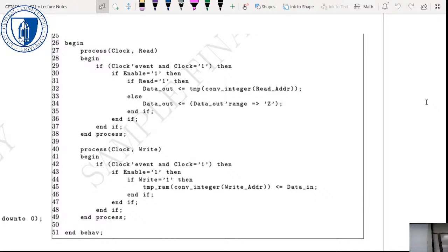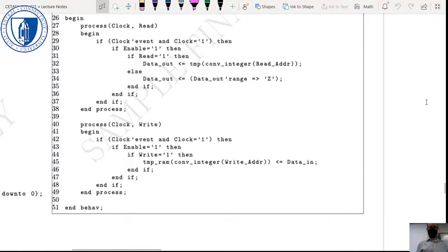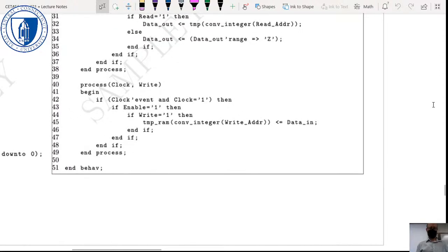I said earlier that everything in VHDL is in parallel, but you can block it up to make it sequential. One way to block things up is to use process statements. That's why if-then-else's work in VHDL, because they're blocked up. Okay, so that's the code. Let's see what the question was asking, if I can figure out where it is.